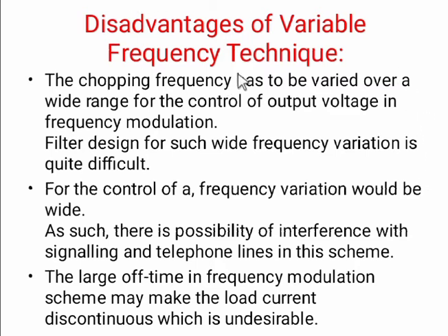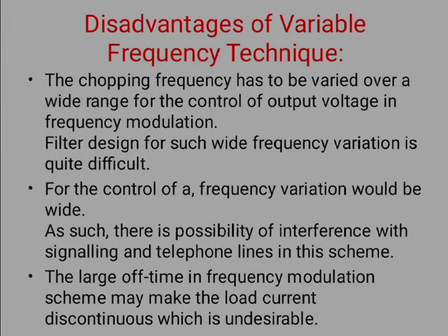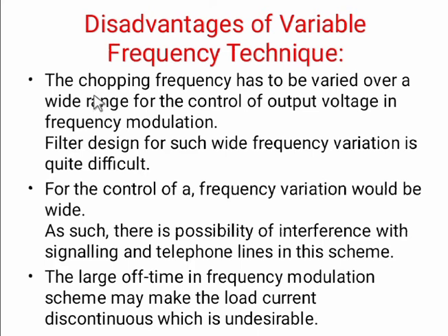Disadvantages of the variable frequency techniques. The chopping frequency has to be varied over a wide range to control the output voltage in frequency modulation. So in variable frequency techniques we have to change the frequency over a wide range to control the output voltage. So filter design for such a wide frequency range is very difficult.